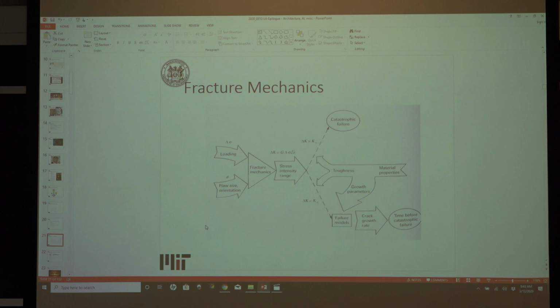So whether we're looking at it from an artistic perspective or an infrastructure or military perspective, it's not that different. You can transfer the knowledge. You have a few known inputs. These would be the critical variables for a sensitivity analysis. What are the inputs into the program? Based on fracture mechanics, it's that initial flaw size. And it's also how that flaw size is oriented with respect to the inspection technique.